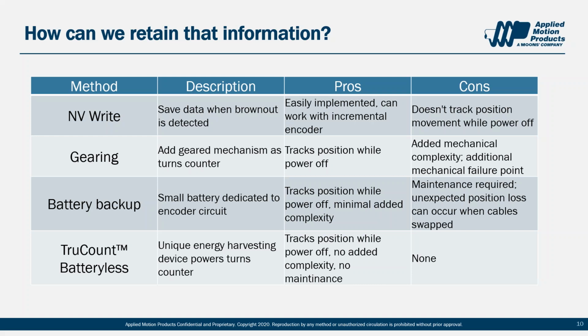It's a great option if you're sure the load won't move during power down, but that's often an unrealistic assumption to make. For example, if you power down the drive during an STO event, you're almost guaranteed that the load will move as it freewheels to a stop. So with that in mind, we know we need to account for power down motion. There's a few common ways this is done.